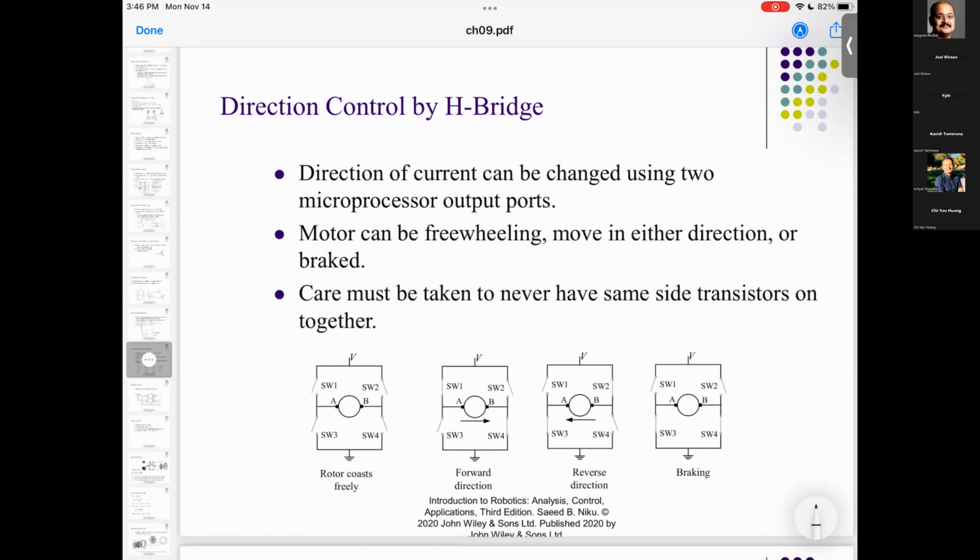There are other actuators. You can have magneto-rheological actuators. Think about it like you have a magnetic fluid, and then basically you magnetize the fluid, and all of a sudden that fluid changes its viscosity and becomes a semi-solid. Or you can have shape memory alloys, wherein you provide some type of input, either temperature or current, and the alloy changes its properties, it displaces.